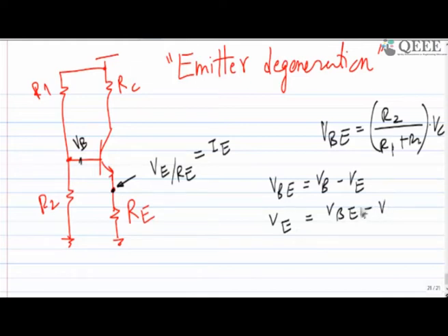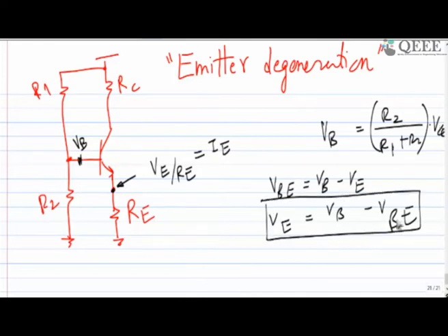I made a mistake there; it has to be VB. VB, this potential, is equal to R2 by R1 plus R2 times VCC, right? And VBE, we know that we want to achieve approximately 0.65 or maybe higher than 0.65. This is our agenda. So you can put directly 0.65 if you want, or if you add some more value.